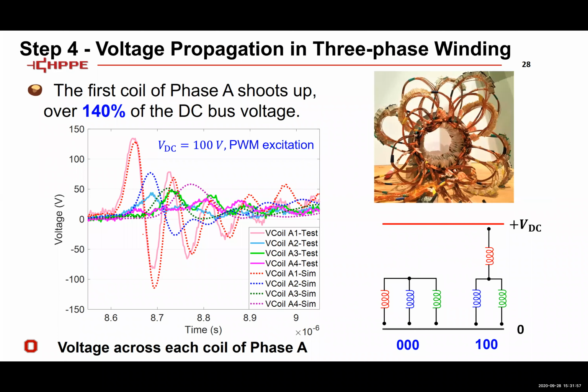Okay, so next is the testing we did for the 3-phase manually wound windings in the lab. When we tried to wind this in the lab, it's really difficult to push as many conductors inside the slot. For the production version, they actually have 96 conductors in the slot, but in the lab we could only put 80 conductors inside there. Also, the end windings are pretty long.